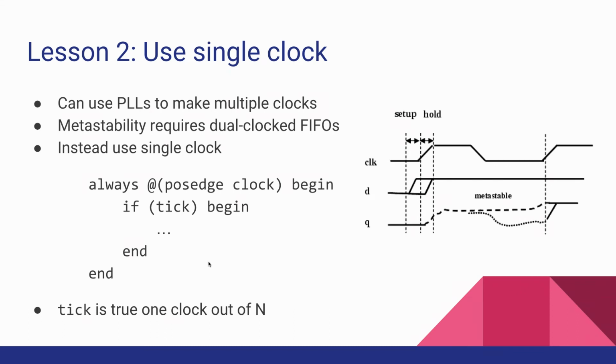So it's generally a really bad idea, and the reason is kind of obscure. I can tell you later over dinner if you want, but basically, you have B plus C on the right-hand side. It's going to be ready and latched into A. The compiler will know for sure that if those two are on the same clock, it'll work. But if they're on different clocks, like you're generating data here and consuming it there, it might latch right when it changes. If it does that, the flip-flop will go metastable. So you have to do all this work to get around that. If you don't, your flip-flops will have garbage in them a lot of the time.